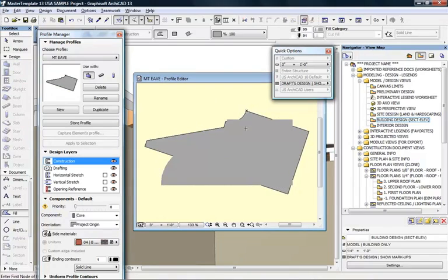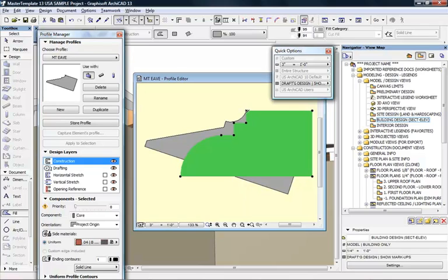I don't need to save any changes for what I just did, but I'm going to paste this in. And this shape here, I will go and drag the alignment point. Now this is critical. This X here is the project origin, or the origin point for this window, and that's where we have control of the profile when we're drawing it.